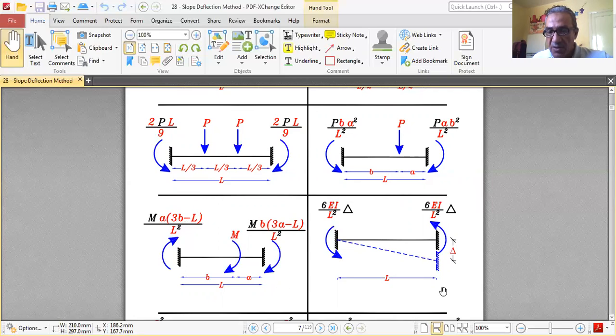Okay. What about displacement of the support? We haven't talked about this one yet. So the previous ones are review, but this is new. For fixed ends and displacement of the support, delta capital at one end and the length is L. The moments at both ends rotate in the same direction. In this case, if it settles down from the right, then they rotate anti-clockwise. If they settle down from the left, then they rotate clockwise. So here they settle down from the right, both rotate anti-clockwise.